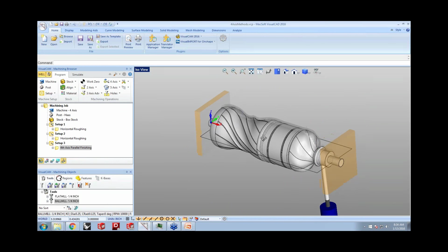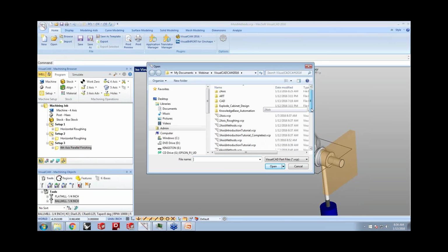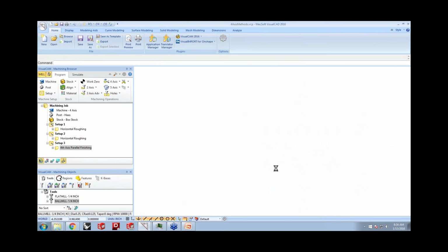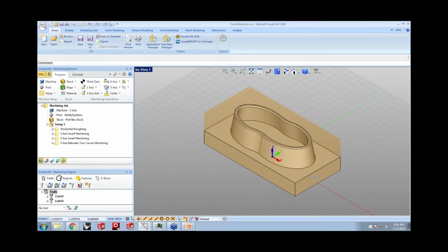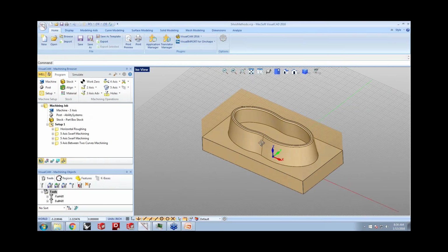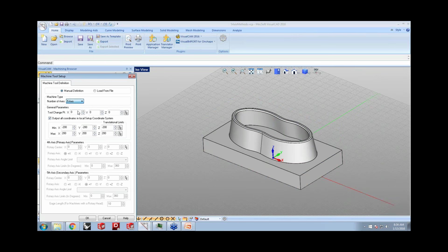The next thing I would like to demonstrate is the 5-axis methods that are offered in VisualMill. So I'm going to go through the 5-axis simultaneous methods, which are offered in our Premium configuration of the product. And the workflow is very similar, so you can bring in a solid surface geometry. You can define your toolpaths. You establish the machine tool to be a 5-axis. You can specify your machine configuration, and you can specify the primary and the secondary axis right up in here.